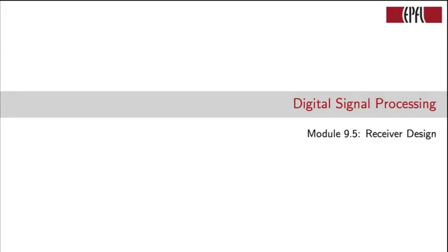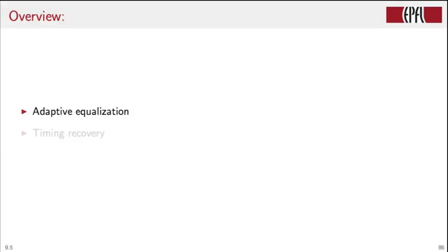A lot of things unfortunately happen to the signal while it's traveling through the channel. The signal picks up noise, we have seen that already. It also gets distorted because the channel will act as some sort of filter that is not necessarily all pass and linear phase. Interference happens too. There might be parts of the channel that we thought were usable and they're actually not. So the receiver really has to deal with a copy of the transmitted signal that is very, very far from the idealized version we have seen so far.